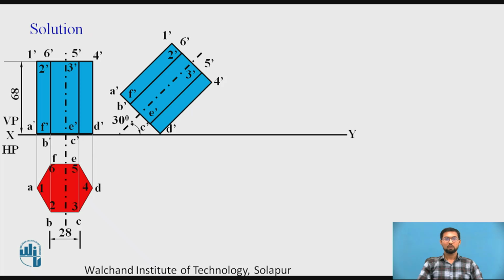Now we have to take an observer from the top side that will observe the hexagonal prism in a tilted fashion, and we have to take the projector lines from the bottom base first, and similarly from the first view of the hexagon.